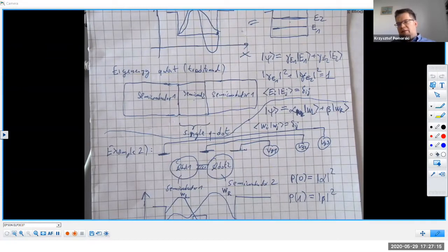So if you only have one eigenenergy populated in a chain of two coupled quantum dots, there is no possibility of implementation of a semiconductor position-based, electrostatic-based qubit. But if you populate at least two eigenenergies, then there is a possibility of implementation of logical state 0 and 1 at the same time. So there is a superposition principle.